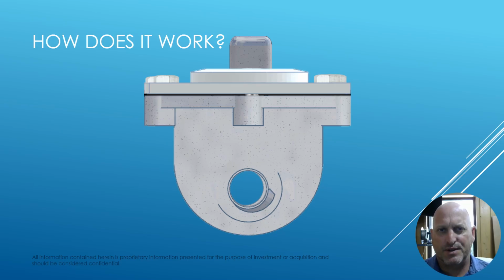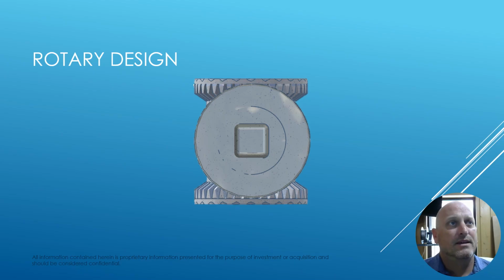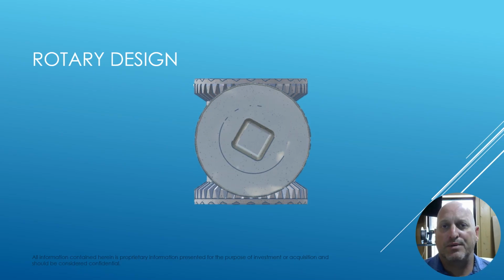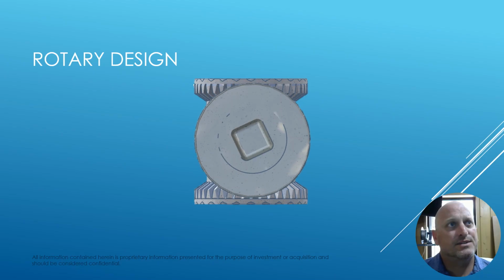extensive service or extreme service valves that need constant attention, like in precipitated calcium carbonate flow or something like that, you can replace the innards on this valve. And there are some valves out there in such extreme service they need to be replaced multiple times daily. This would save a significant amount of expense just by being able to replace the interior parts. If we're looking at it from the top, the pinion will drive both the plate gears,